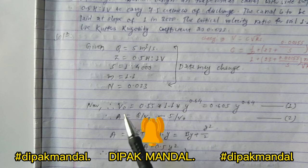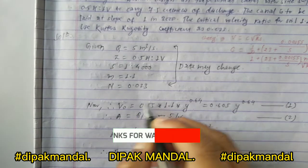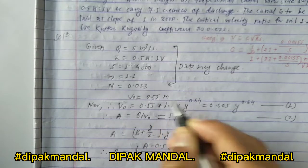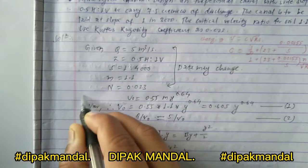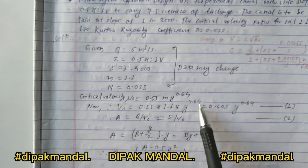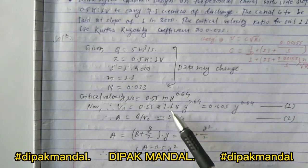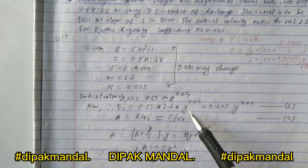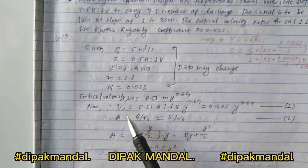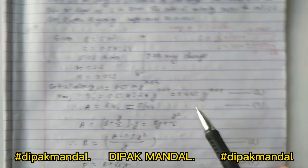Very first step, as we already discussed in the last video, we have to calculate the value of critical velocity. For the critical velocity we use the formula V naught equal to 0.55 m into y to the power 0.64. We keep the value of m given in the question, m equal to 1.1, and y is not given, so we keep y as usual. So the critical velocity V naught becomes 0.605 y to the power 0.64. Let's assume this is equation number 1.